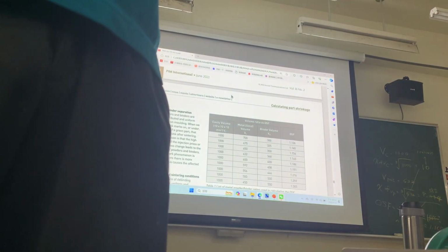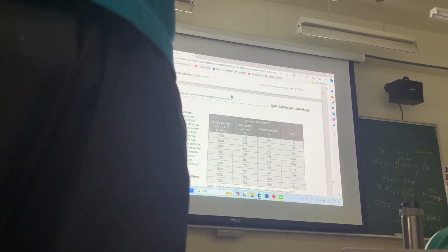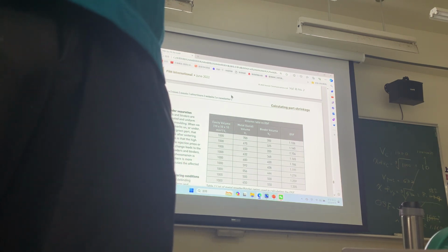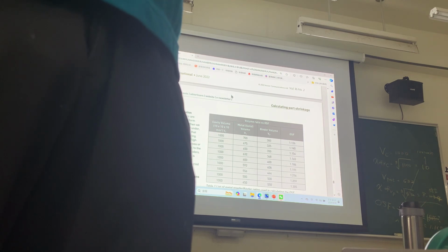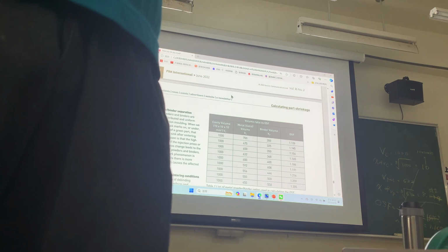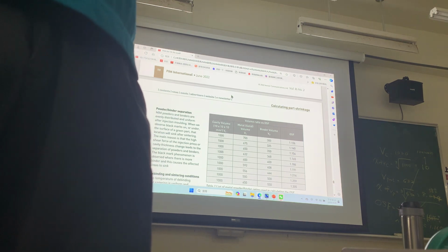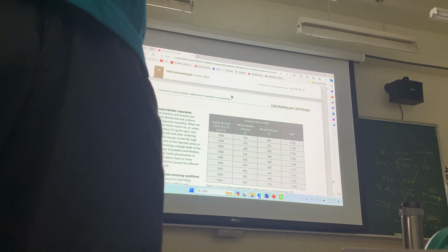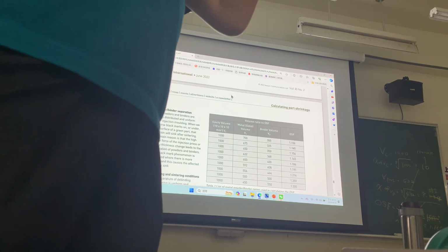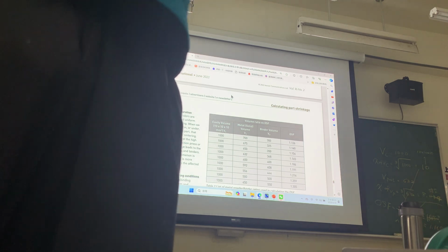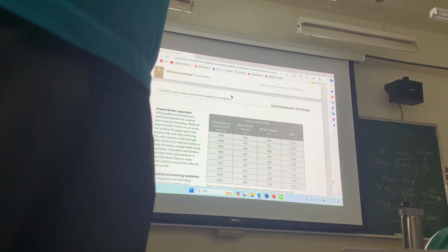For MIM to be successful, the key point is the powder should be what kind of size, what kind of microns. Remember? 13, 14? Which one? Okay, please everybody remember 13 microns. Lower than 13 microns, this equation will approach perfect. Okay, 13 micron. How about your hair?